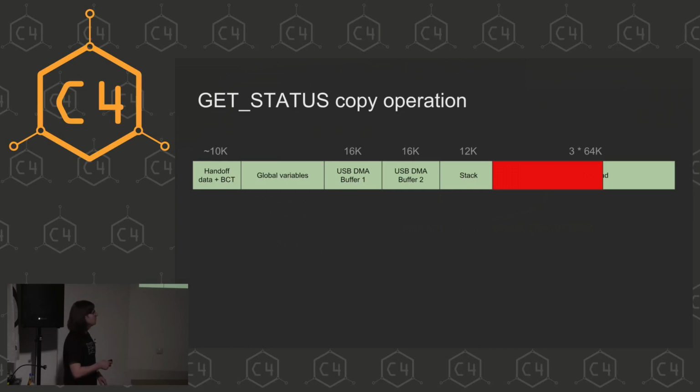On the third transfer, this is used again. You can just count how many USB packets you send, and then you know when you used buffer 2 or buffer 1. If you are currently in buffer 1 and you want to switch to buffer 2, you can just send another byte over the bulk endpoint, for example, and then this buffer is being used, and then it switches over to the second buffer.